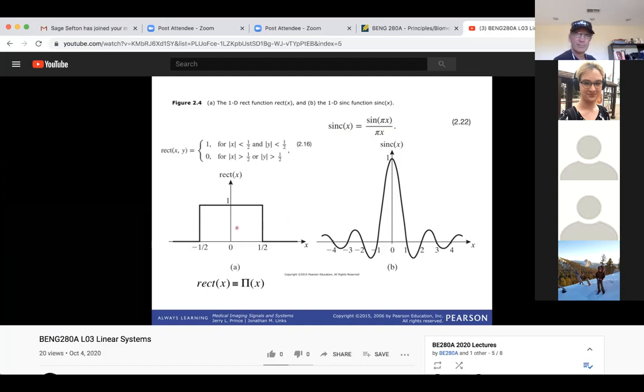So those two things are called conjugate pairs, and you're going to use this a lot. The Fourier transform of a rect function. What does that mean again? If I want to build this function using sine waves and cosines, as with a Fourier expansion, the amplitude of my coefficients go as this function. So I have constant amplitude out to this spatial frequency, and then it drops to 0. So it has only a finite number of spatial frequencies that are needed to build this function.